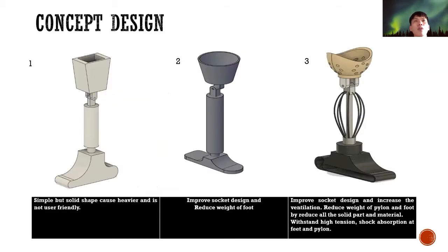In this slide, we'll talk about the conceptual design. There are three conceptual designs I have designed. The first one is very simple, but this solid shape is heavy and not really user friendly. And the second one, I improve the socket design. It becomes round and I reduce the weight of the foot. Whereby in concept 3, I improve the socket design and increase the ventilation. I put a hollow and reduce the weight of the pylon and the foot by reducing all the solid parts and material.